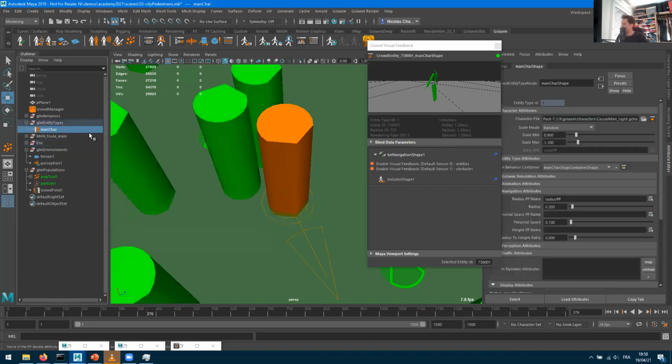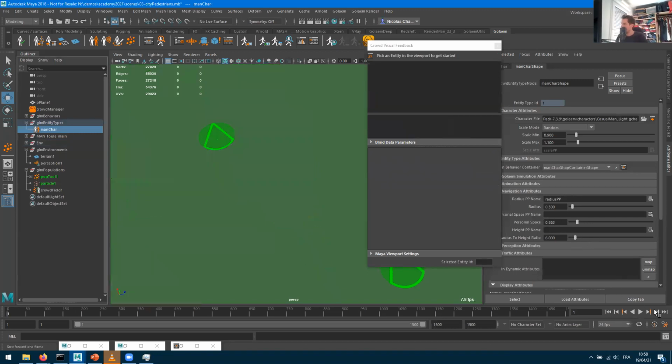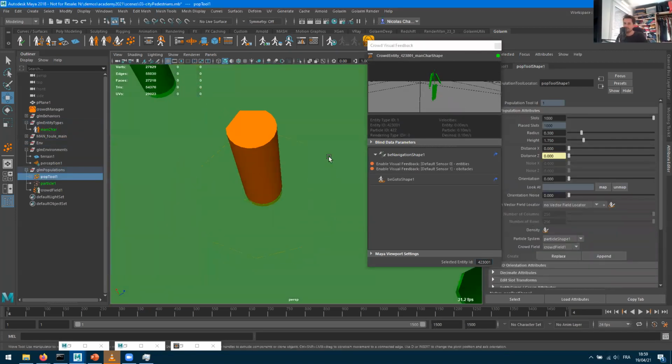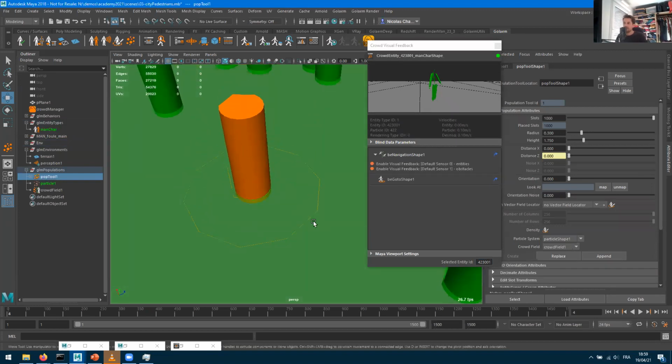More space around me: the personal space is a percentage of the radius. So 0.8 means 0.8 of my radius. The next time you run your simulation, you've got a space in which you do not want to have people. Please take into account that we're going to try to respect this, but it's not a hard limit. If in some situation we don't have any other answer, some people will enter that zone. So personal space is something we tend to keep free from other people, but we can't always.